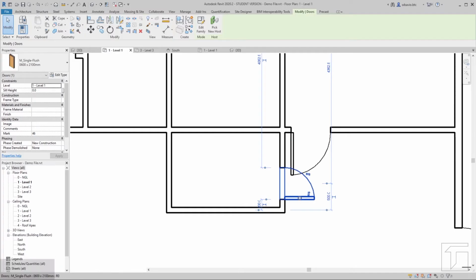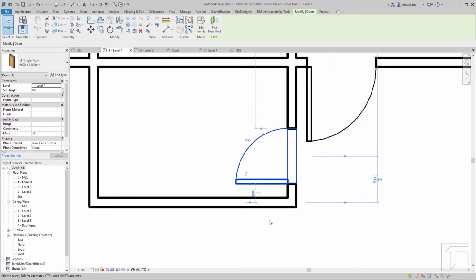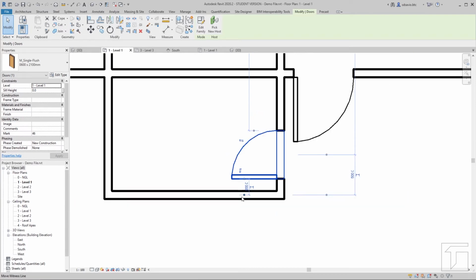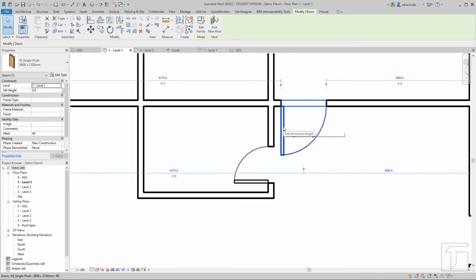So going back to Revit, let's just click on this horizontal flip and it will flip it instantly like that. So the beauty of Revit, right? So again, let's double check. So again, this is already correct, 200 millimeter space. And then this door here we select.